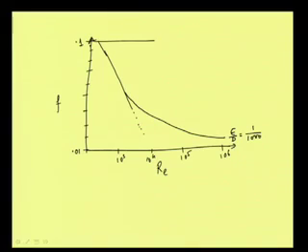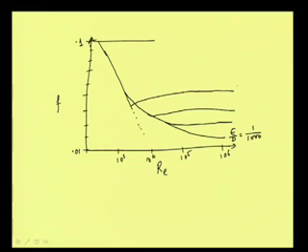Okay. So, that way this is going like that. Then with more roughness, our value is increasing like that, and the curves are changing like that. Say for epsilon by d, a large epsilon by d value may be 1 by 30. If the diameter is 30 and the roughness is 1, then we get this sort of curve. Now, this sort of curves can be used.